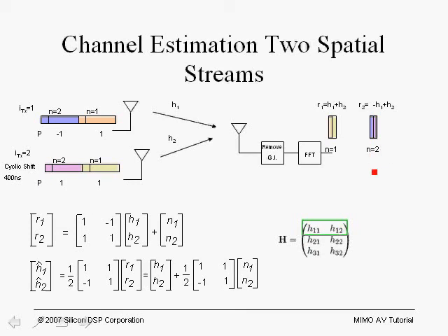If we organize them in terms of, and write them down in terms of the vector operations here, then once we receive R1 and R2, we pre-multiply them times this matrix here, which is the inverse of the P matrix, and we recover the estimate of the channels. Of course, these are noisy estimates. Now, very importantly, we have to point out that the inverse of the P matrix is a unitary matrix and does not enhance the noise.